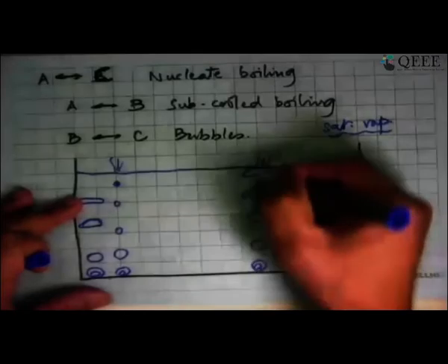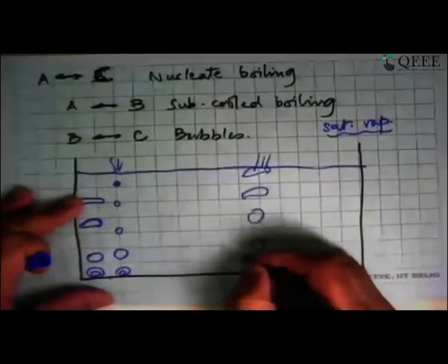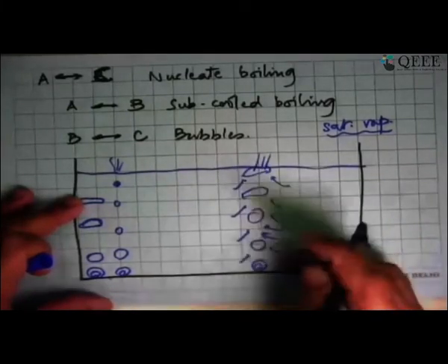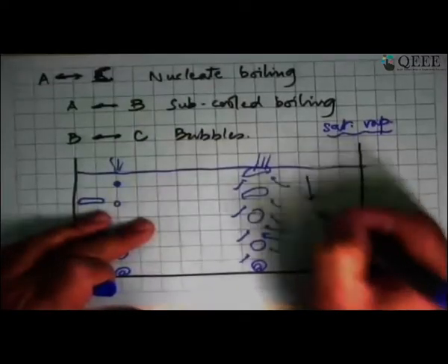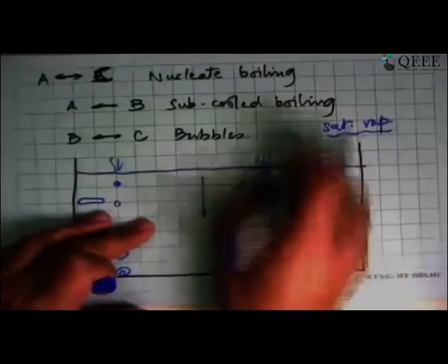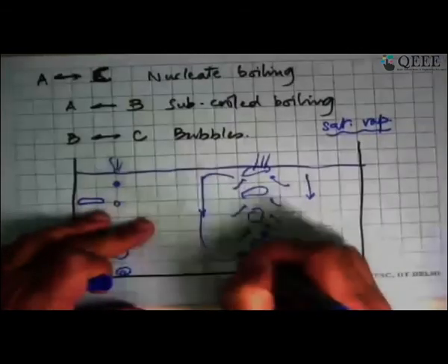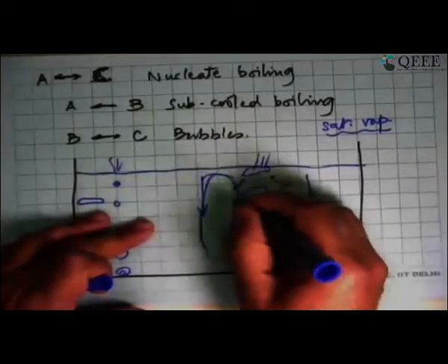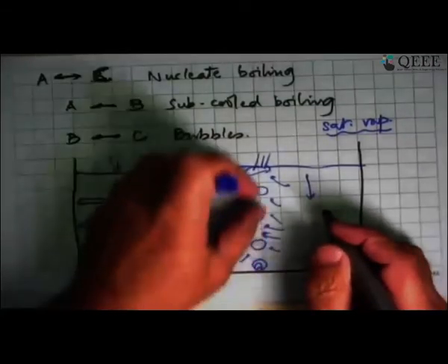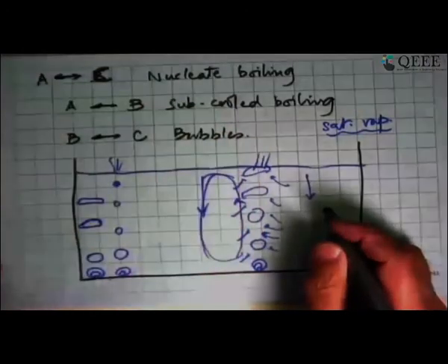And what this bubble movement does is that as it moves up, it keeps causing the fluid around it to come behind it. So it gets the fluid coming in here. So there has to be a flow that is going there and coming there. So this bubble is moving up and it will induce a downward flow and set up a circulation, which is something like this. And for that, one looks at the dynamics of the bubble, that as the bubble goes, what does it do to the fluid that is there.